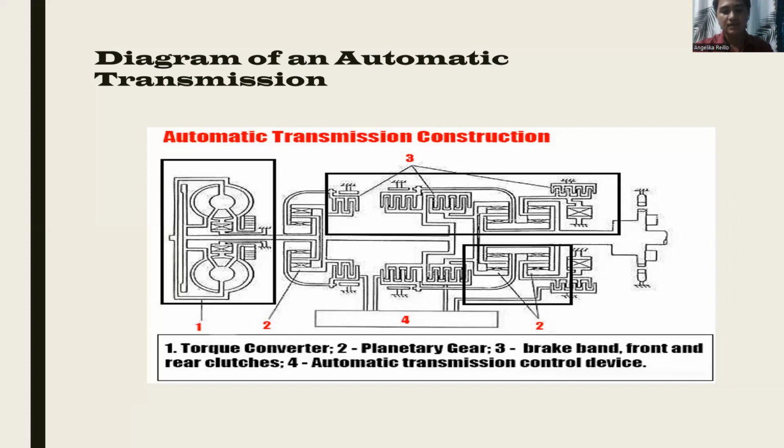Brake band, a device designed to block elements of the planetary gear set. Valve box, a system of channels with valves and plungers, the function of which is to control and manage. The main function of the valve body is to convert the vehicle speed, engine load, and gas pedal pressure into hydraulic signals. Thanks to these signals, the friction blocks come into operation sequentially, going on and out of the operation state, thereby changing the gear ratio in the automatic transmission.